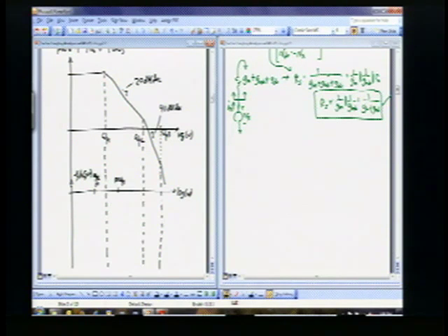And so after one pole, so say there's only one pole in this circuit right here, where will the phase end up after one pole? 90 degrees different. Exactly, 90 degrees. So the phase starts out at 0 degrees here, but then it's going to end up at this 90 degree level. And I'm also going to draw on here in preparation for the next pole a 180 degree.